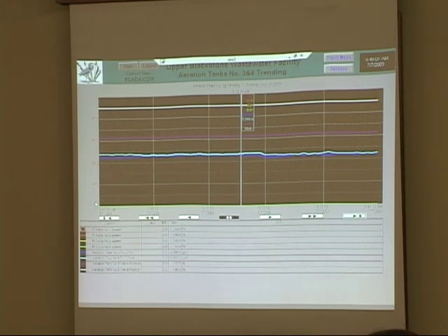And you notice the scale right here. Right now it's 0 to 100 for the pump speed. So I can say, okay, that's about 90%. If I want to know what the scale is for the aeration flow, I just click on that and see how it changed to the blue. So it gave me the scale. So the trends have a lot of tools with them, and even if you knew it and you haven't worked in it in a while, it's just a reminder of what the trends can do. So they're a very good, useful troubleshooting tool.